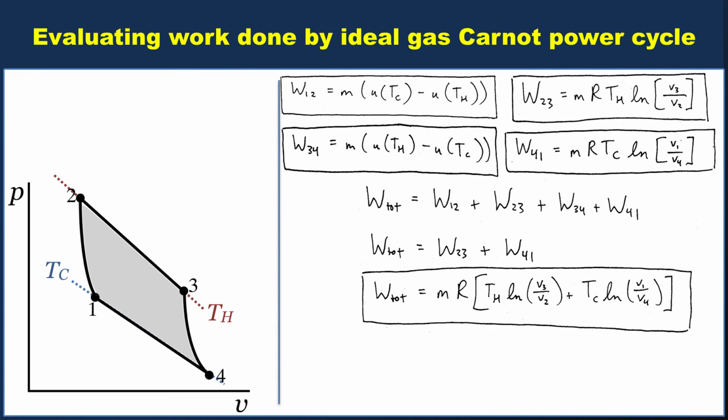We put that together, it's just the terms involving the natural logs. And remember, you can go back through if you don't like ratios of specific volumes. You can rewrite those as pressure ratios using the ideal gas law. Likewise, any term you see that involves an mRT out front, you could, of course, rewrite as a PV for that particular temperature, again using the ideal gas law.